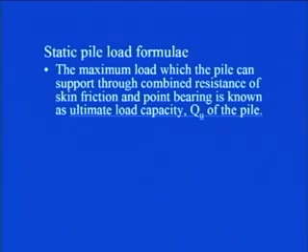So, whatever the distribution or however it is getting transferred, the load which is coming on the pile, that is compressive load from the superstructure, first gets transferred to the pile shaft in the form of frictional resistance. Once that stage is over, where Q becomes equal to QF, if Q goes on increasing beyond that, then that increase will get transferred to the point bearing.